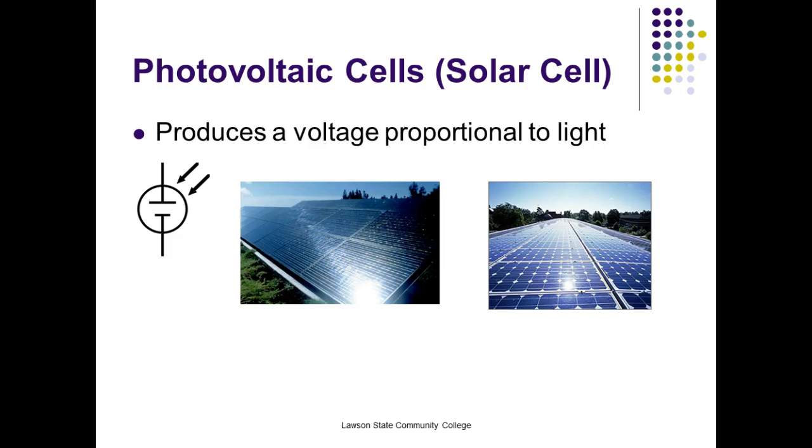So we don't get much voltage out of them, but if we hook voltage sources in series, then their voltage adds, right? You understand. If you hook them in parallel, then they're what? Then their current adds. So that's what these big old solar arrays are. We don't call these solar cells; these are technically called solar arrays. So what do they do? Well, they hook some of the cells in series to get the voltage they need, and then they hook those in parallel to get the current they need. I think Harbor Freight sells one that's like a 45 watt, and it comes with a lot of stuff with it.